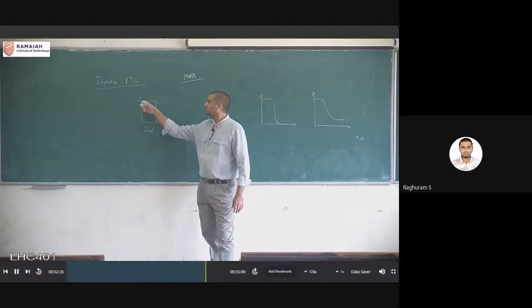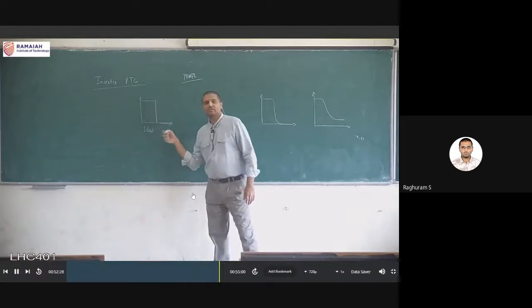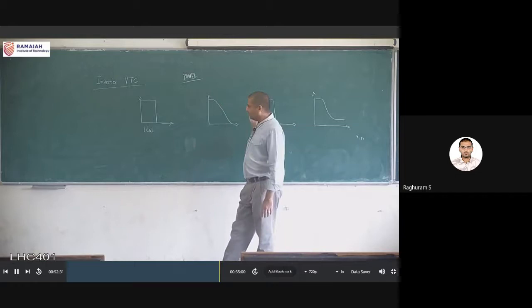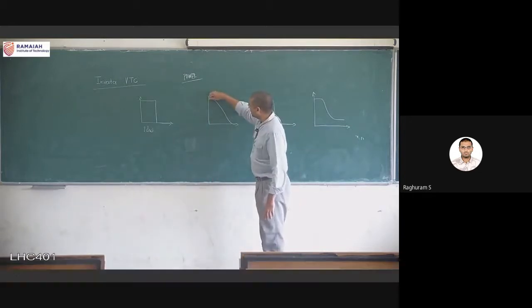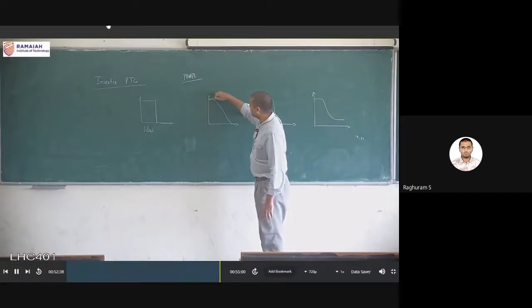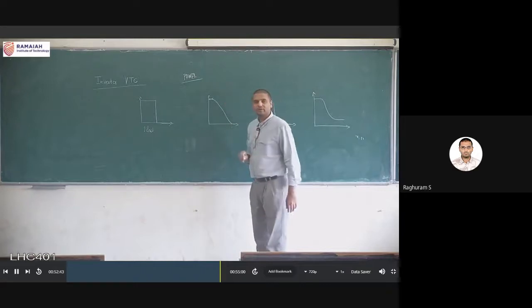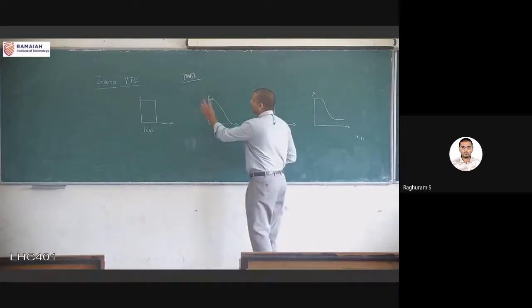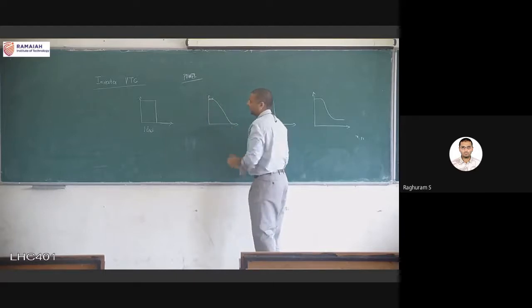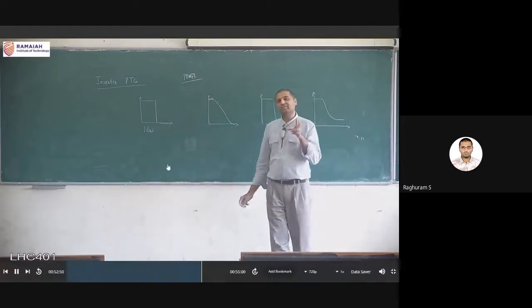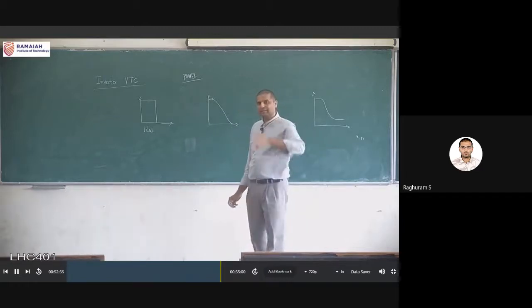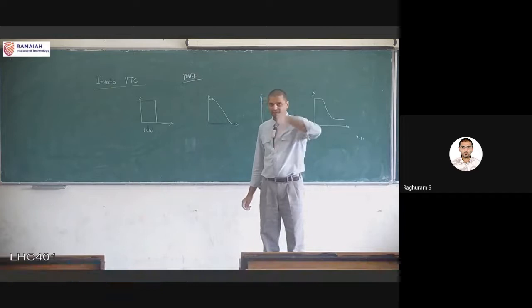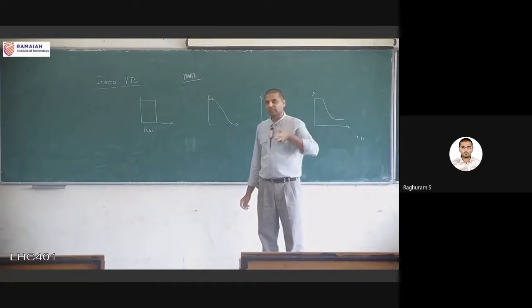Okay, in this case power consumption is 0 during the operation. Because the switching happens instantaneously, but in the real cases switching doesn't happen instantaneously. Here maybe a small region as long as the voltage is constant, and here, okay, there is no power consumption. Why is there no power consumption? Because in this small region and this small region, one of the transistors is off, and if one of the transistors is off, current cannot flow in that circuit because there are only 2 transistors in series. If one is open circuit, current cannot flow.